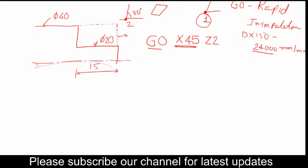If it goes very slowly from point number 1 to point number 2, it is just a wastage of time. And since no machining is happening in this movement from point number 1 to point number 2, we can call it a non-cutting movement. Okay. So did you get the meaning of the first line? It is G0, X45, Z2.